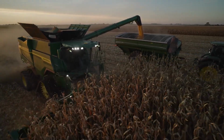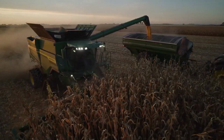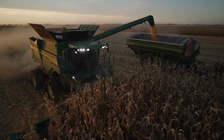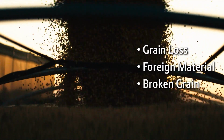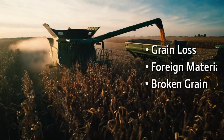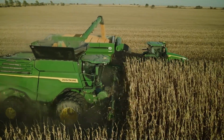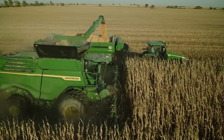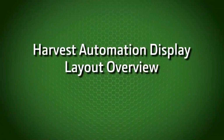Rather than being reliant on the operator to make the necessary internal settings adjustments at the right moments to achieve desired results, Harvest Settings Automation shifts the operator's focus towards harvesting-based job outcomes, specifically grain loss, foreign material, and broken grain. Utilizing these three inputs collectively, the automation system will make corresponding internal combine setting changes to achieve and maintain the user-defined quality standards.